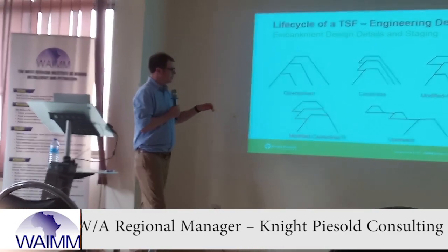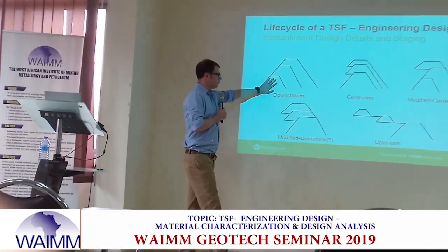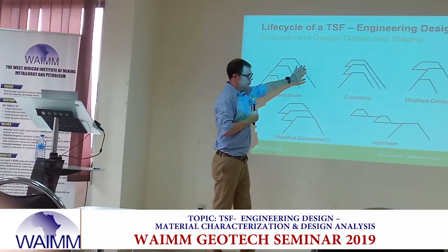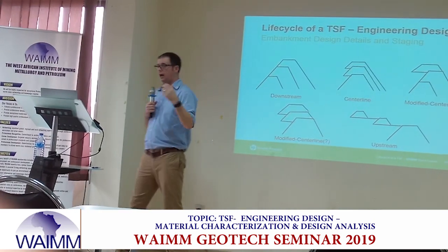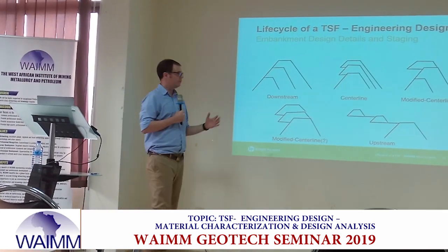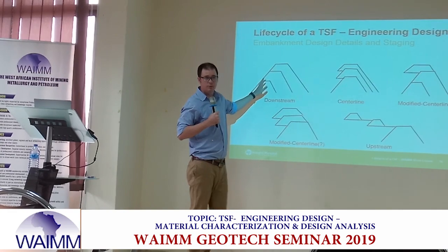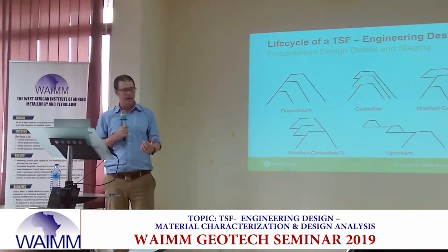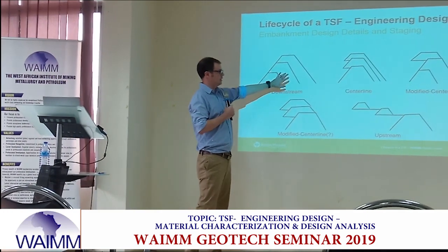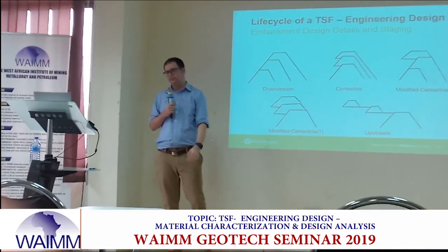So here's what these various facilities look like. Downstream raise, we've got our starter facility. Each of our raises goes sequentially downstream. The benefit here is we don't rely on the tailings for strength. We have continuity of our upstream face. If we were to use something like a geomembrane liner, it's very easy to install in that manner. We typically can use things like rock fill for our structural fill.